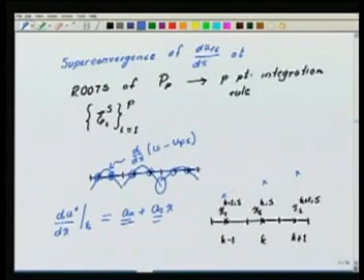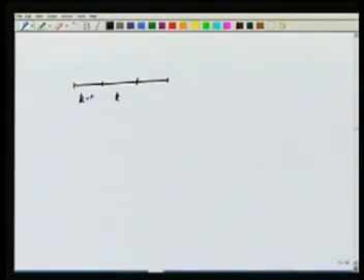So I would like to obtain, using this information, the straight line fit, and I hope that this straight line fit is essentially equal to du/dx. Now how do I construct this straight line fit? Remember I am doing it for the element k, so I have to do it for each element separately, find these coefficients a0, a1, and from there construct the variation of du star/dx in the element k. So again I take this neighborhood, k, k minus 1, k plus 1.